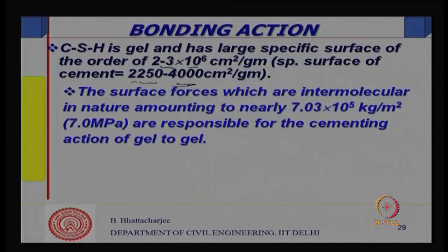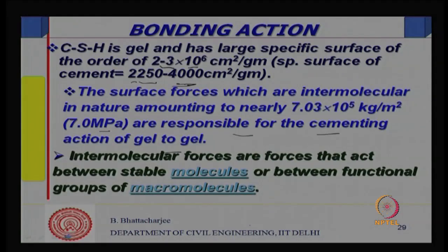And the surface forces, which are intermolecular in nature, of the order of around 7 MPa, are responsible for the cementing action of gel to gel. So, gel to gel cementing action is because of intermolecular forces, what are called van der Waals forces, and we will come to that. Intermolecular forces are those that act between stable molecules, between functional groups, between macromolecules.